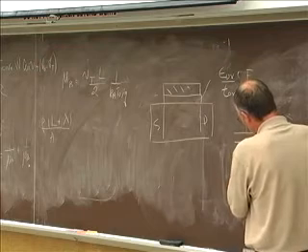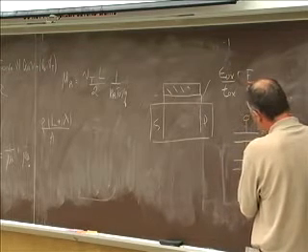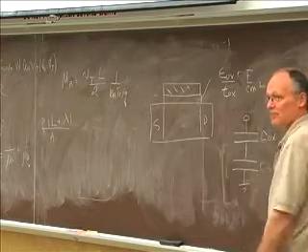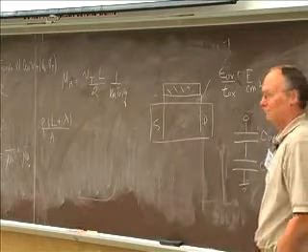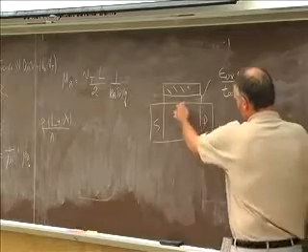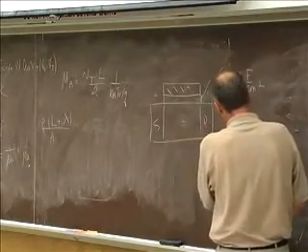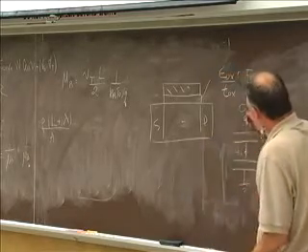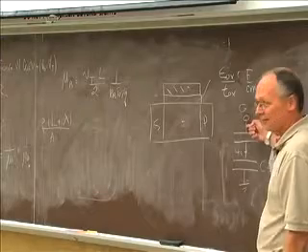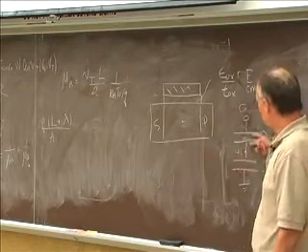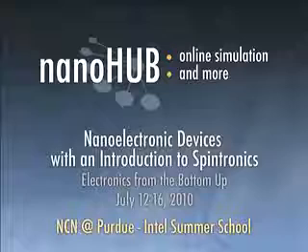But it also has in series with it a semiconductor capacitance. Sometimes people call this the quantum capacitance. These two are in series. So here's my gate terminal. Here's the surface of the semiconductor, or the middle of the channel. And the actual gate capacitance is the series combination of two capacitors.